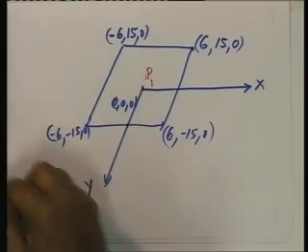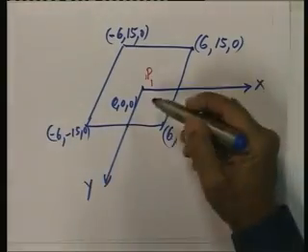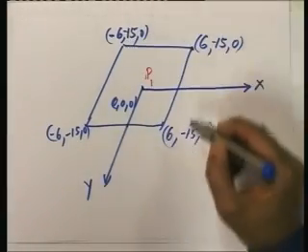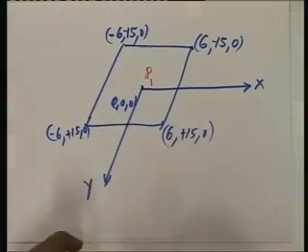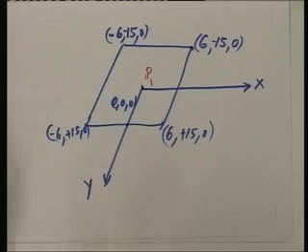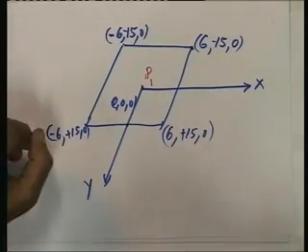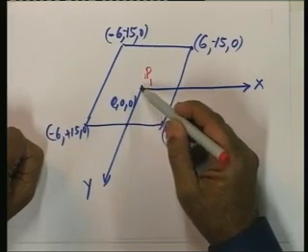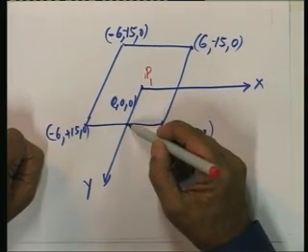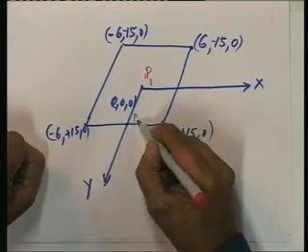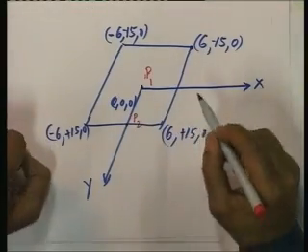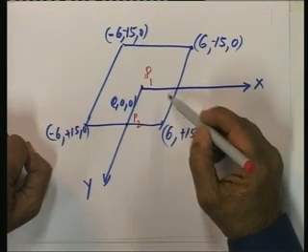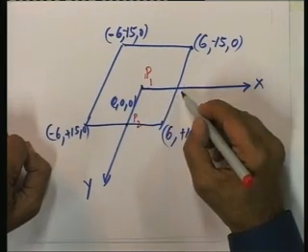Let me just make a small correction in this. The y coordinate is positive in this direction and therefore these two will be minus and these two will be plus. With this correction, point P2 will lie at 0, 15, 6. P3 will lie at 6, 0, 6, that means the x coordinate is 6, the y coordinate is 0, and the depth is 6.